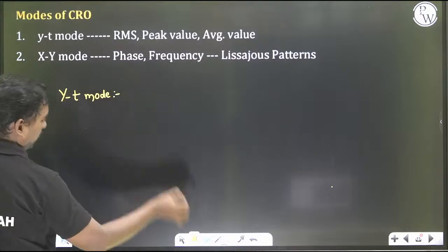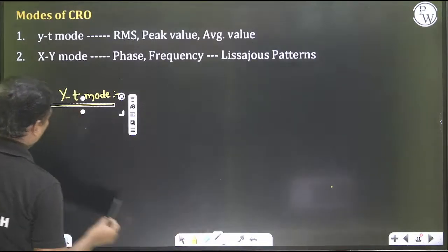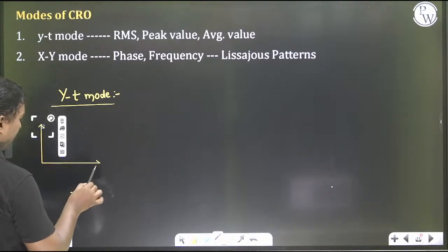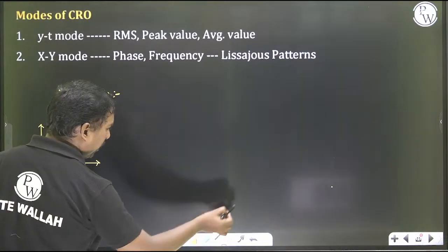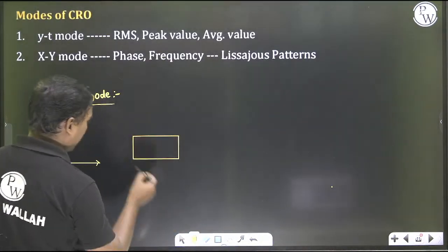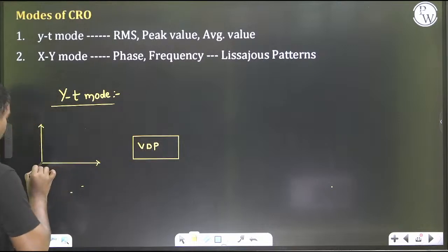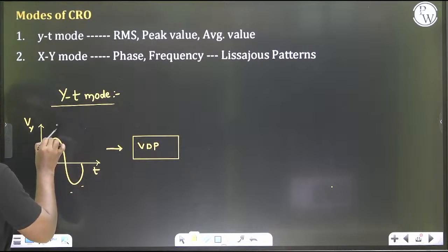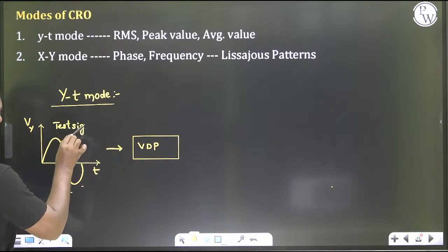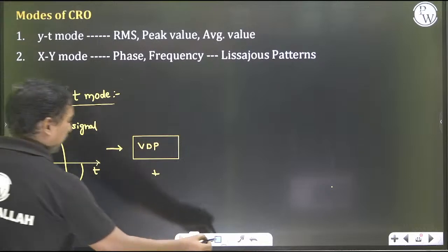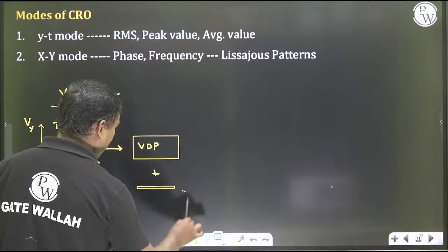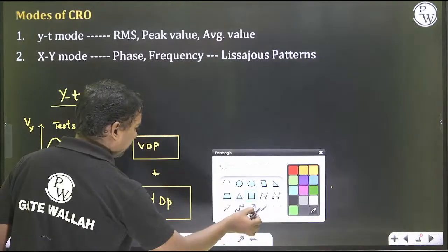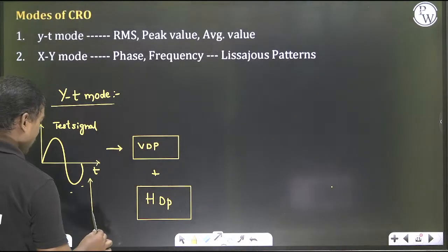If you see this YT mode, for the vertical deflection plates we are giving the test signal. So this is a Vy with respect to time. This is a test signal. For the horizontal deflection plates, we are going to give the time-based signal.